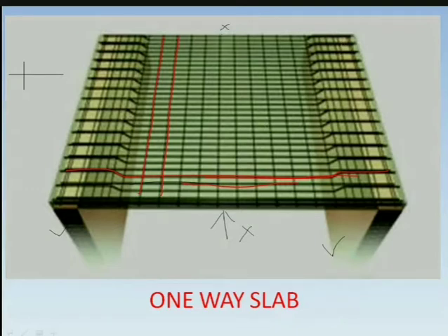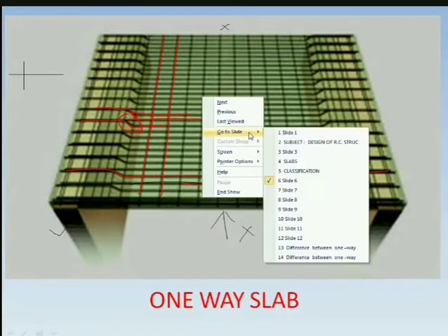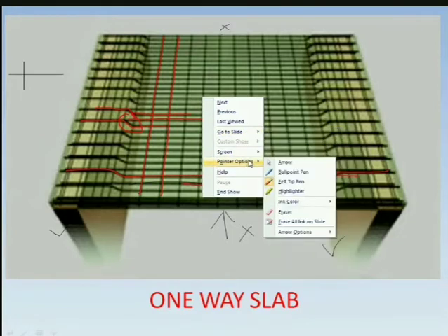So you can see here. Okay, one bar has gone like this. Other bar here is straight. Then next again, one bar is bent. Other bar is going straight. Okay, so this is nothing but alternately bent, so that the bar gets anchorage into the support.